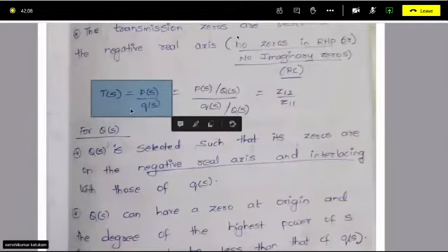Similarly, if I say band pass filter, it will allow frequencies within that band. For a band pass filter, a lower cutoff frequency and a higher cutoff frequency will be mentioned. Within those two cutoff frequencies, the signal will be high, and at other frequencies, the signal will be low.